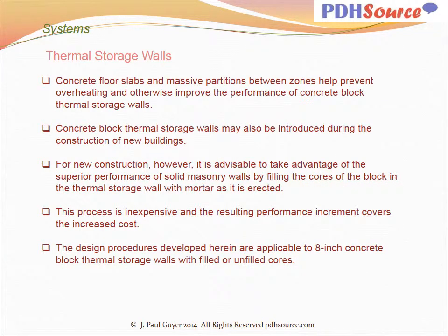Concrete floor slabs and massive partitions between zones help prevent overheating and otherwise improve the performance of concrete block thermal storage walls. Concrete block thermal storage walls may also be introduced during the construction of new buildings. For new construction, however, it is advisable to take advantage of the superior performance of solid masonry walls by filling the cores of the block in the thermal storage wall with mortar as it is erected.